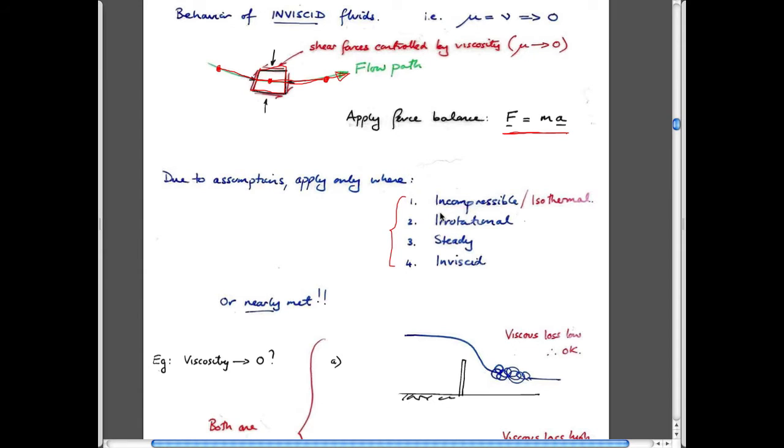Fluids have to be incompressible. And so that's sometimes a little misleading. We know that liquids are typically incompressible because they don't compress very much by definition. And gases, as in the air that we're sitting in, are typically somewhat compressible. But that's not the whole thing, because we could actually use Bernoulli to solve the problem of the air hitting that truck at San Francisco International.